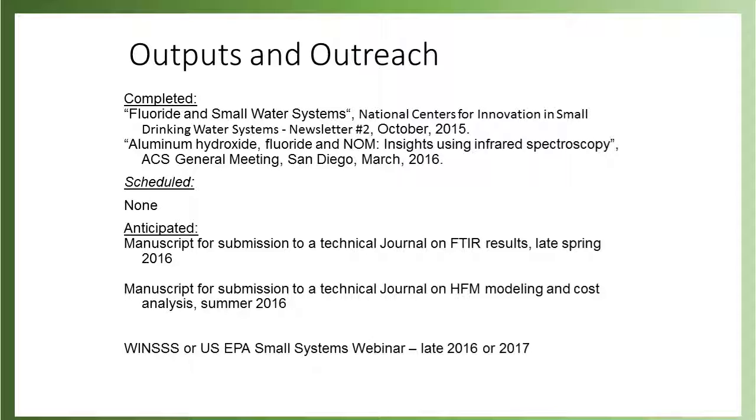Fluoride is actually preventing some of that removal, so you don't end up coming close to meeting the DBP precursor regulations, because you reach the point of diminishing return. Fluoride is not a very common problem, but where it happens, it really happens. It impacts this issue considerably.